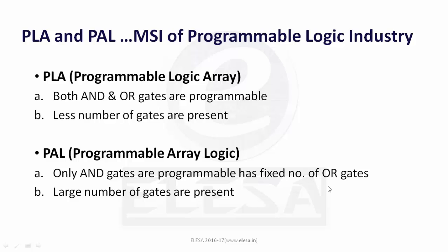That is, you cannot configure the inputs of the OR gates, they are already programmed, and you are allowed to change the AND gates only, but it uses a large number of gates as compared to PLA. So these are the basic building blocks for the PLD, and these are known as the MSI of the programmable logic industry. MSI is medium scale integration.